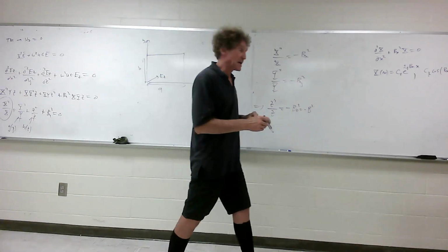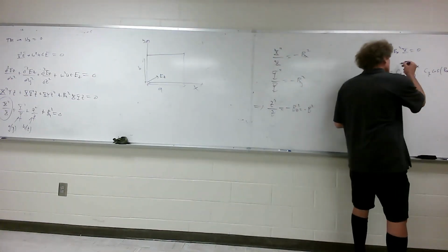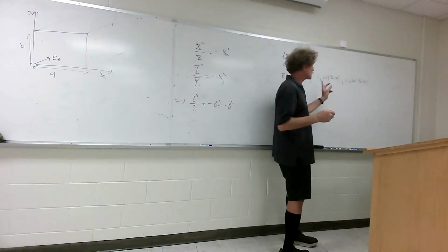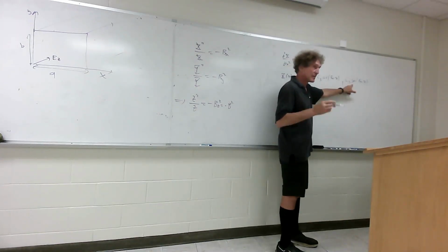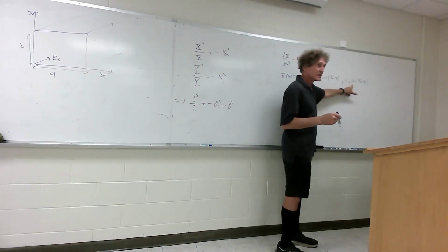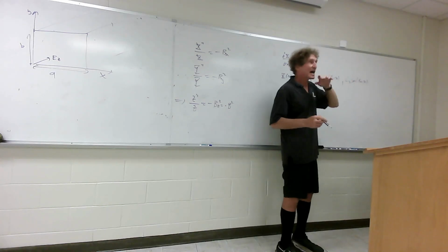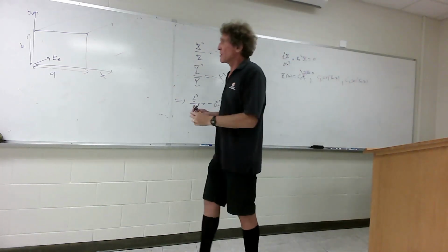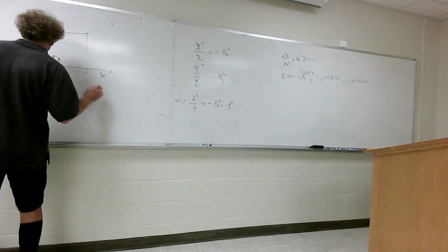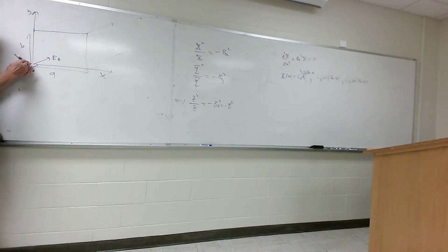Now look at these solutions. It's not propagating, so this one goes away. And it's one of these two. And here's how you always obtain the correct solution. When you look at this, you think, I need the E field to be 0 at x equals 0, right? And it has to be 0 all up and down x equals 0. Do y'all follow me?